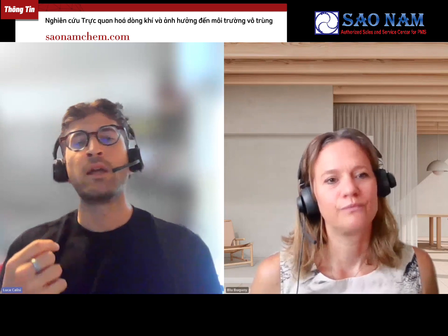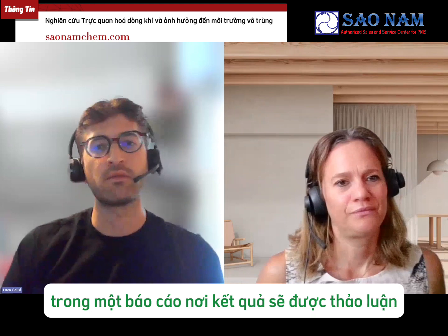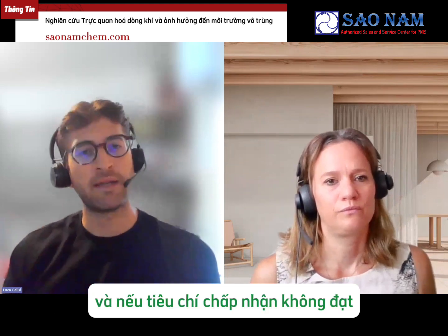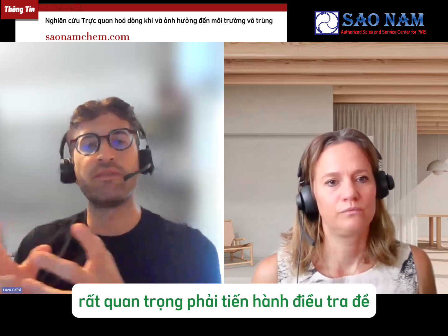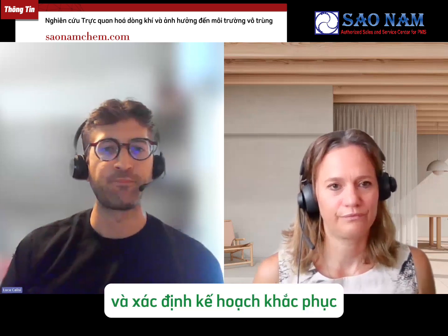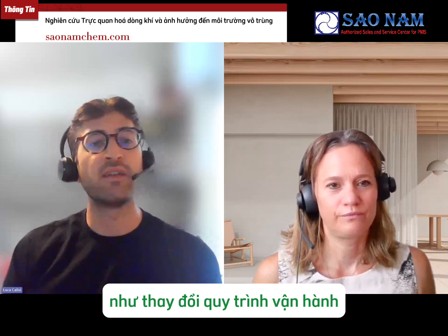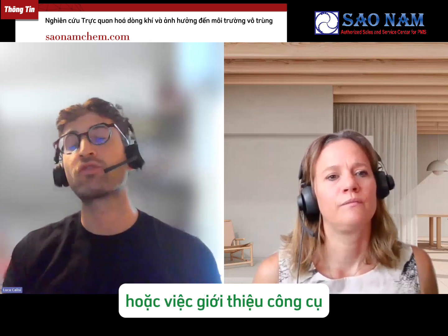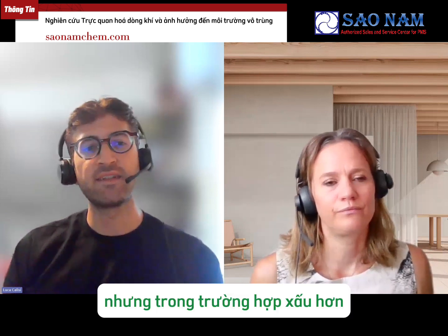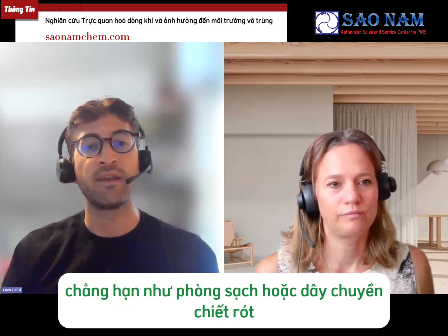As we said, the results of the study should be recorded within a report where the outcome will be discussed. And if the acceptance criteria are not met, it is essential to perform an investigation to identify the root cause and define the correct CAPA plan. Some CAPAs with a low impact are, for example, changes in operating procedures or the introduction of tools during the aseptic manipulations. But in worst cases, a change of, for example, the clean room or the filling line can be necessary.